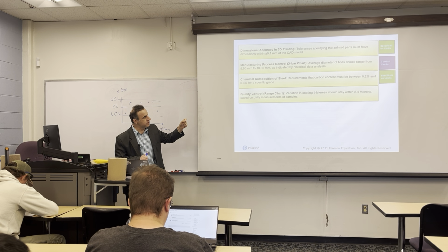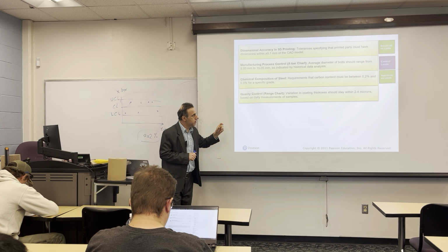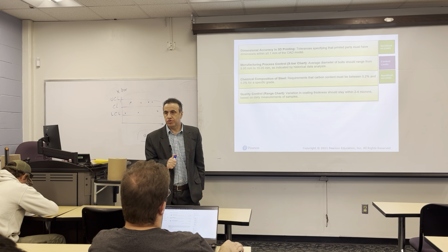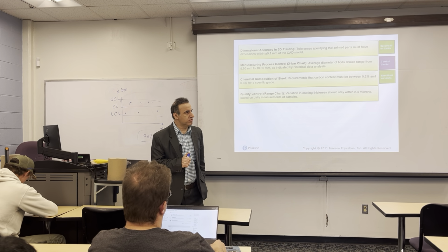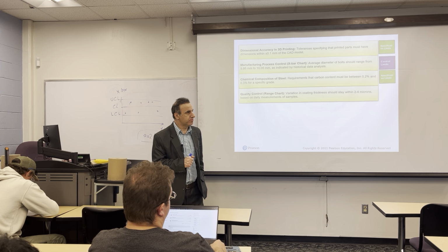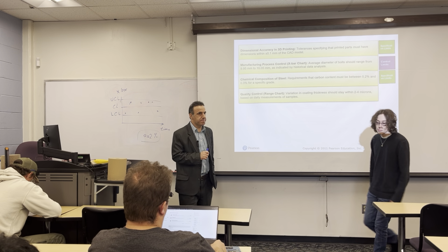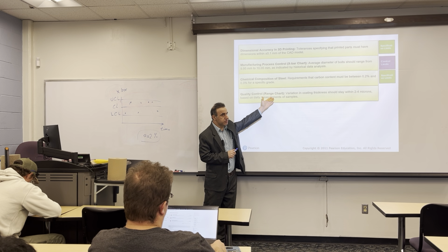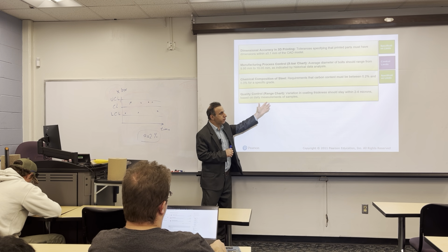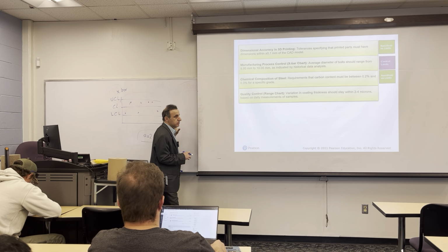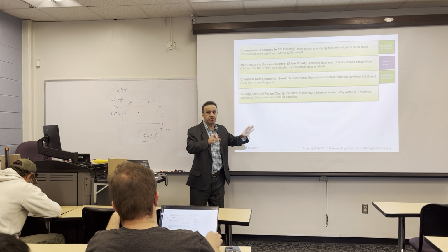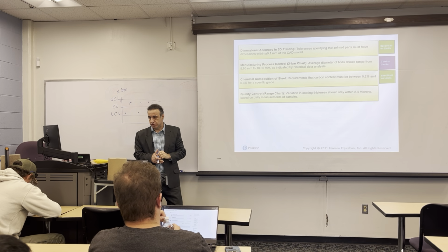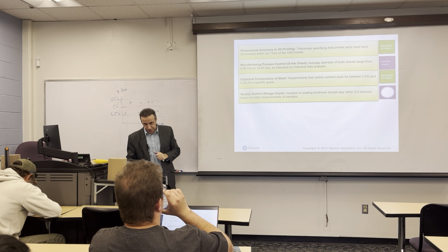Variation in coating thickness should stay within 2 and 4 micron. Control limit or a specification? It's coming from chart. When it's coming from this chart, that is control limit. It's related to process, not customer. So control limit.